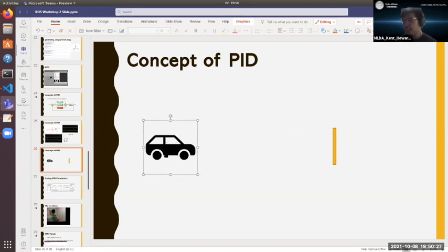They increase the KP and see if it does better. If it does better, they keep the increase, or they decrease the KP and see if it does better, then they keep the decrease of the KP. Otherwise, it will keep the KP at the same value, but increase it by a smaller amount and repeat all the time with the P, I and D. So it's similar to machine learning training. This method is, if I'm not mistaken, prone to local minima.